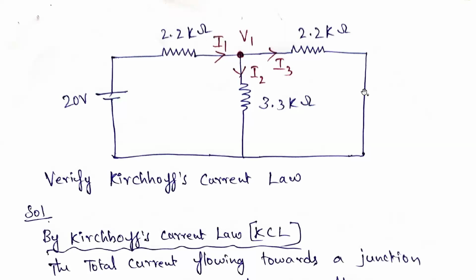This resistance you consider as a ceiling fan, and this another load as a washing machine. Like that, all loads are connected, so one voltage source is connected with all loads. So the voltage is constant. In the power sockets in our home, wherever you test with your multimeter or voltmeter, you will get 230 volts, but depending on the load, the current varies. Depends on the load type.